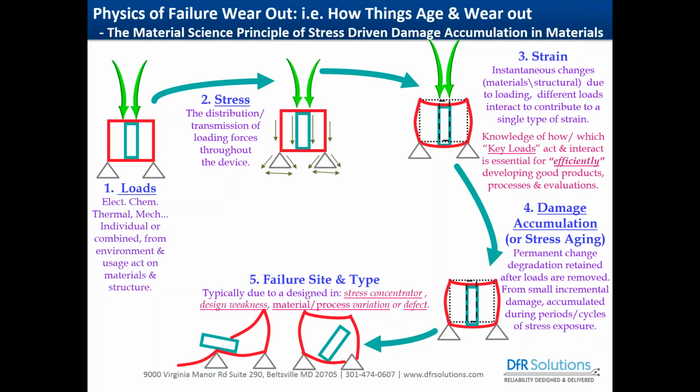And that skinnying down or pinch point is going to become a hot spot if that trace has a high enough current load. And then we also have to worry about material and process manufacturing variation from making strong parts to weak parts, and sometimes that goes to the extreme of some of the parts being out and out defects.